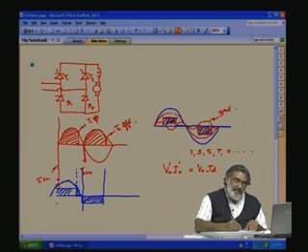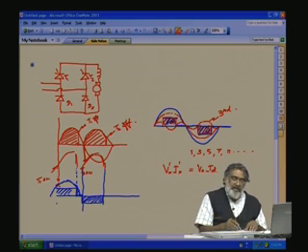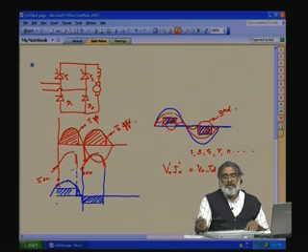See here, this is the voltage we got. Now, this voltage will have the fundamental at the output side as well as the harmonics. So far we have talked about only the DC value, but if you see the voltage waveform across the load, you have this type of ripple waveform coming. The ripple voltage will have ripple harmonics also, other than the DC value. Here it will be 2 times the fundamental, then its other multiples will be there. So, this harmonic voltage will generate its own harmonic currents. These harmonic currents at the load side can create losses.